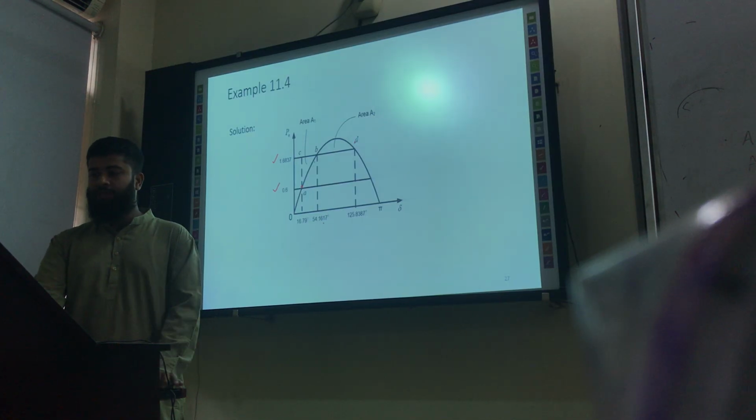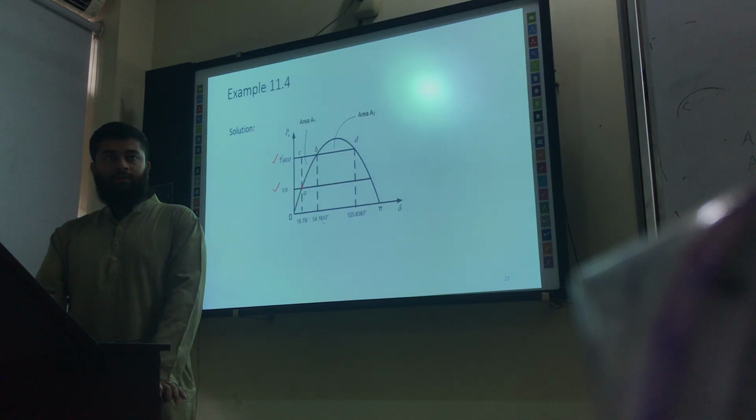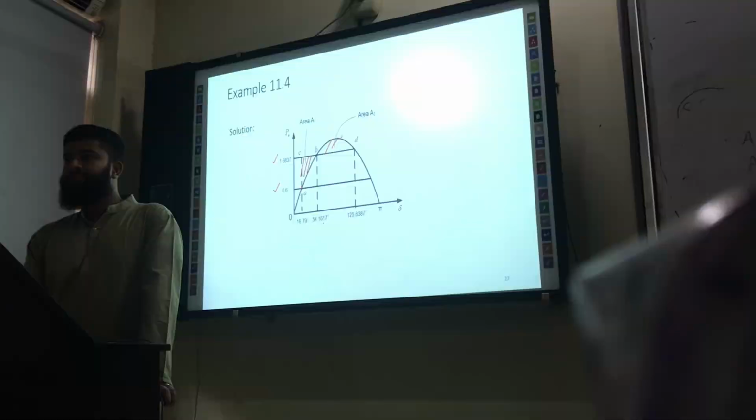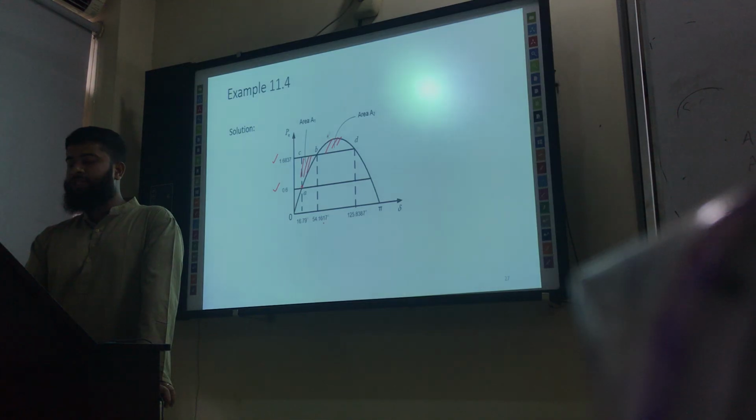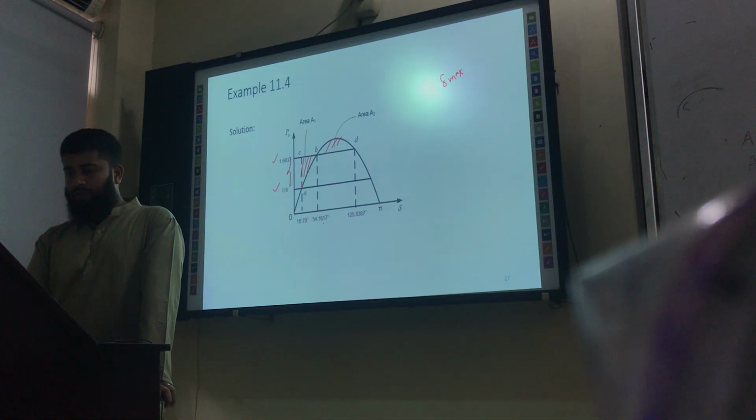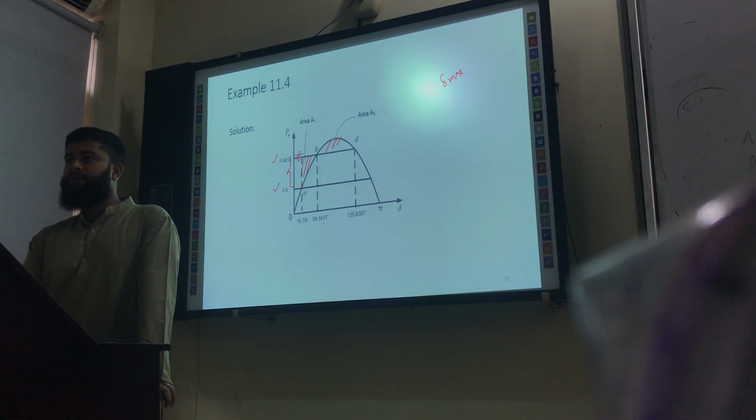And obviously, as this is at the limit, right? So this area and this area should be same, right? Because initially we actually applied this equal area criterion method, and then we actually got the expression of delta max, right? And as this is at the limit, if you just cross this boundary for PM1, then the system will be in the unstable state.